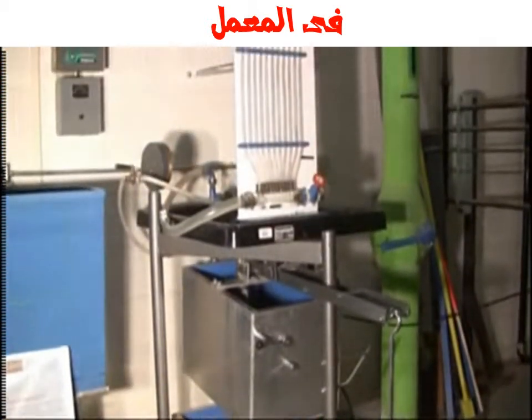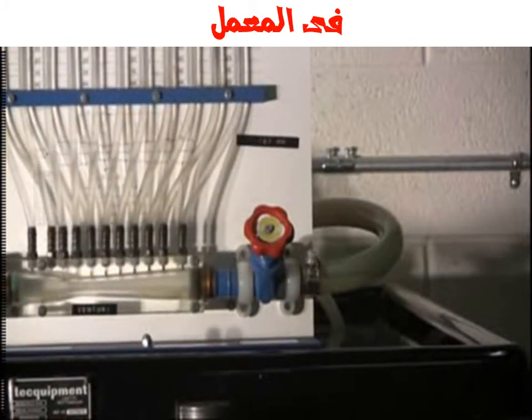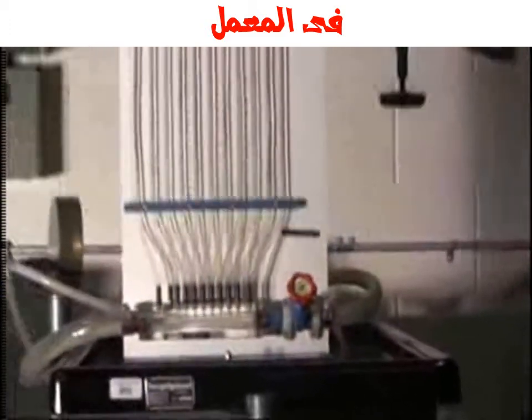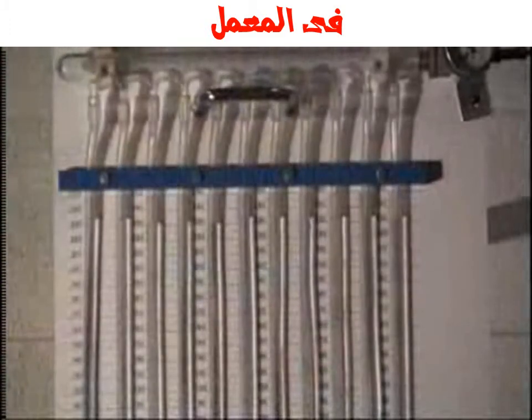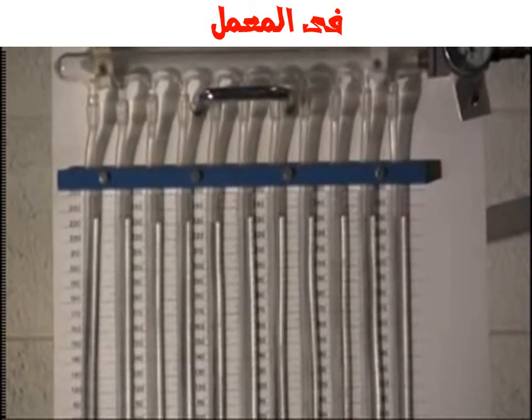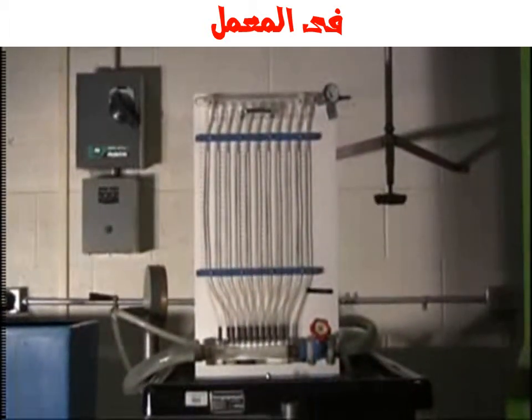Now we will check that the apparatus is set up properly. First, make sure that the red valve is completely closed by turning it clockwise. Ensure that the piezometer levels are reasonably equal and high enough, but not off the reading scale. If not, please alert the teaching assistant.